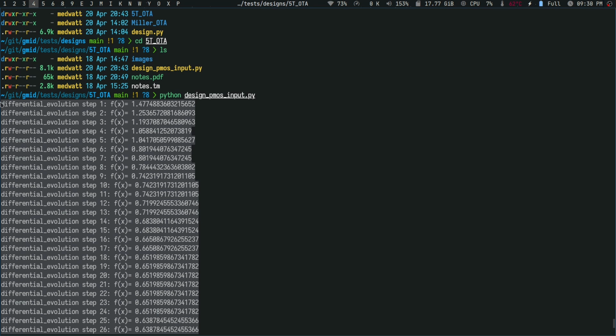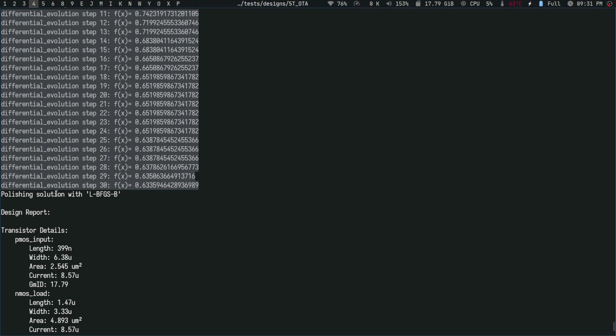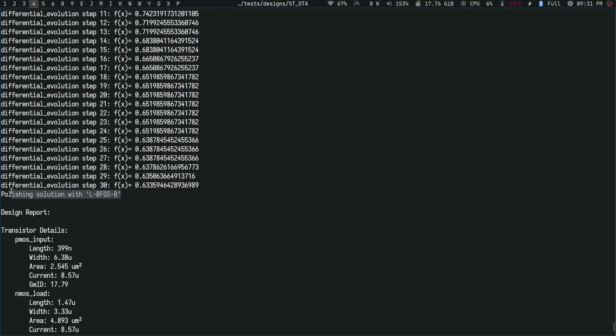So what I decided to go for right now is to explore the design in order to have some global optimization, which means that you can search the design space. So you have local optimization and global optimization. Local optimization means that the optimization tool can get trapped in a local minimum, whereas global optimization searches the whole space in almost a random manner, and then it finds one good spot where we might have the solution. From that good spot, we can then narrow down with a local optimization like this one.